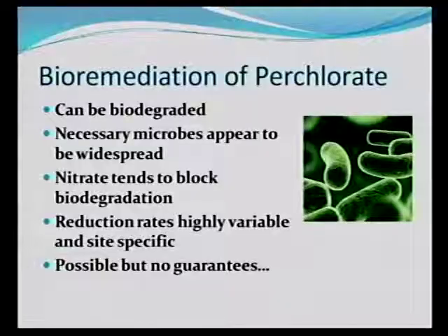Perchlorate can be bioremediated. This has been shown in ex situ systems. If you can introduce the chemistry that you want and the microbes and all that other stuff, you can certainly biodegrade it. The literature is a little bit sketchy when it comes to in situ biodegradation because there are other compounds that can block the natural biodegradation of perchlorate, but it's potentially possible to biodegrade perchlorate in situ.